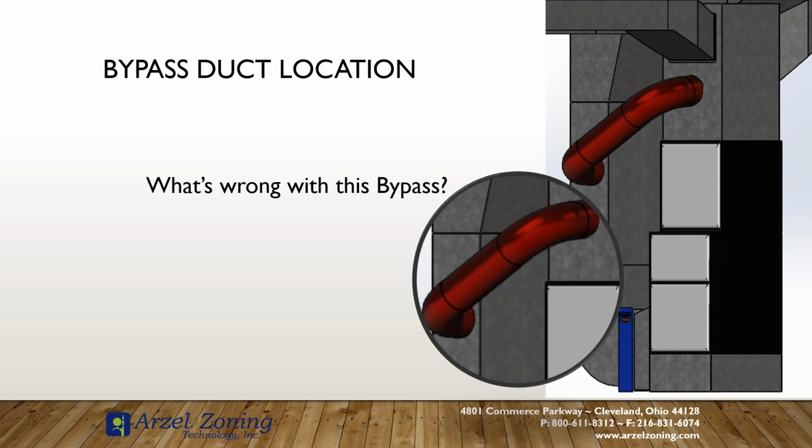So I'm superheating my return air and I'm going to run my limits, or I'm supercooling my return air and I'm going to tank my coil temperature, and that's going to have huge performance and efficiency impact on the equipment itself. So you're taking the point of the greatest BTUs and dumping it so close to the furnace that there's no chance for it to temper itself with the air coming back from the home, and we're going to really hamper the efficiency of our equipment by doing that.